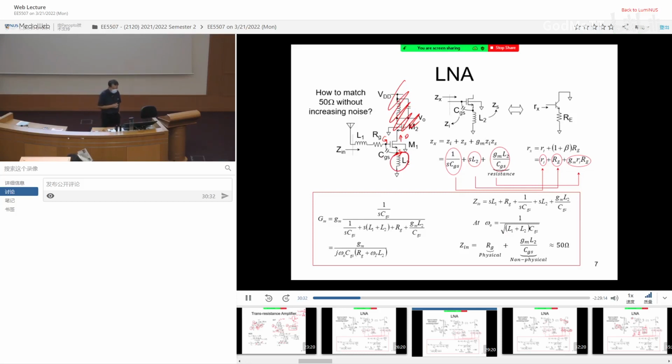Now to derive this is going to be very, very tedious. So I'm going to borrow what we learned when we derived the reflection rule for the BJT. In deriving the BJT, if you look into the base terminal, the equivalent resistance, Rx, is given by the transistor resistance, which is Ri, and then this additional term, Re, boosted by 1 plus beta.